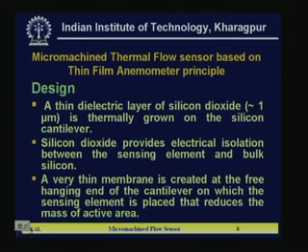So the silicon as well as the thin film resistance whose change you are going to measure would give a combined phenomenon. In order to isolate this combined effect, we normally put an insulation or isolation layer between the metal film and the semiconductor material. And what is the purpose of using the semiconductor material, you can ask me? The purpose is that we can micromachine that semiconductor material, in particular the region where the thin film metallic resistance is placed, so that its thermal mass will be less. So the heat absorption or heat dissipation by the base material will be less, and whatever the dissipation of the film is, it is only due to the flow pattern.